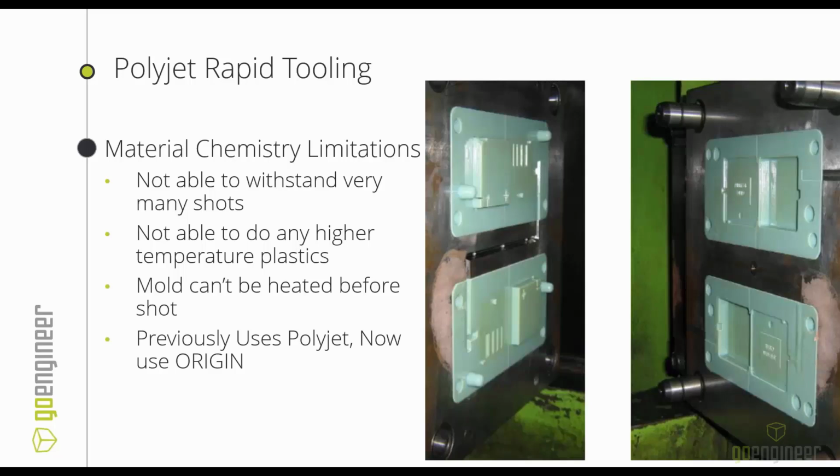So we couldn't do very high temperatures, and you couldn't do very many shots. You could still verify your design with these. Print it, set this thing up, get this all going for a couple hundred dollars. Do a handful of shots in it, verify that your design works, and then say, okay, now we can go spend $50,000 to have the tooling made and have confidence that it's actually going to work well.